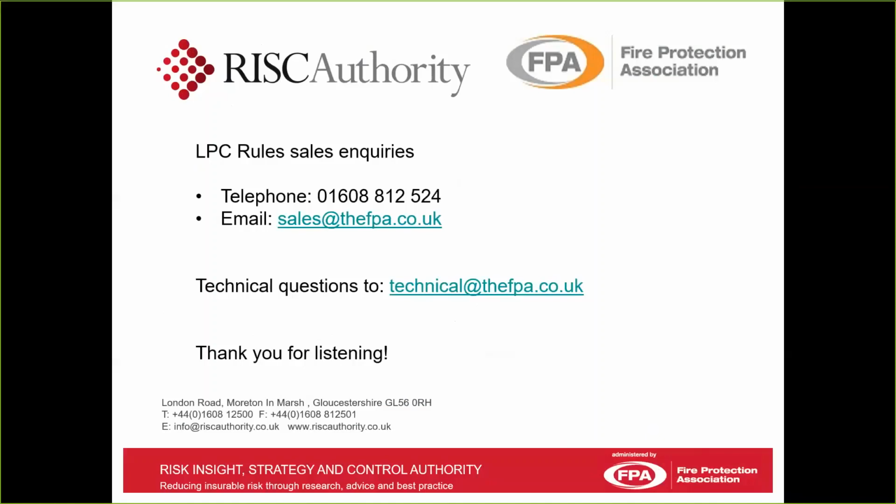Another question, some water authorities are nervous about water from sprinkler systems being discharged into the water course. So we've kind of covered that one as much as we can in TB237.2.1b. So when you read the whole document, you'll see that we've covered that particular aspect as well as we can. There was another question about the need for this flushing document and whether in fact some of the aspects in the TB are entirely necessary. Well, in terms of NFPA and FM, what TB237 does is it doesn't overstate the need or the means of flushing, so we don't feel that it's necessarily any more than it needs to be.